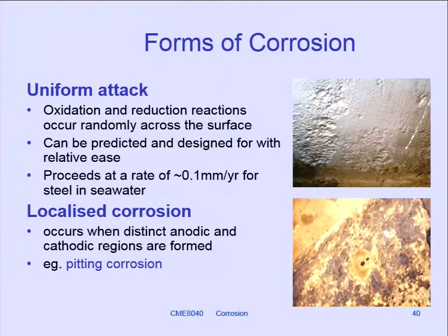And you have to be pretty careful about that because there's a factor of 25 there, 25.4. So they quite often call it MPY, milli-inches per year, and we've got millimetres per year. And this is a factor of 25 between that. So 25.4. So you've got to be a little bit careful.